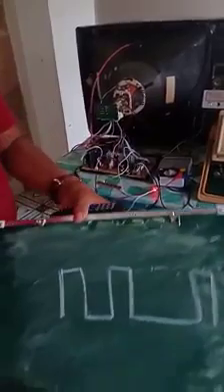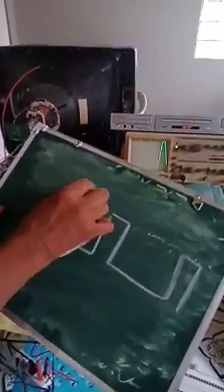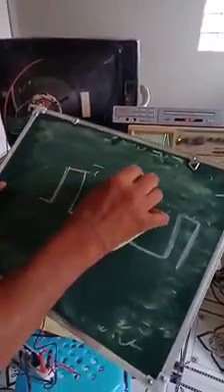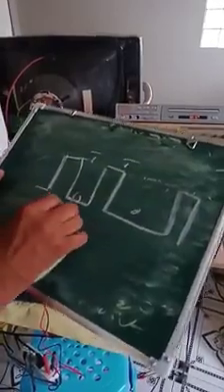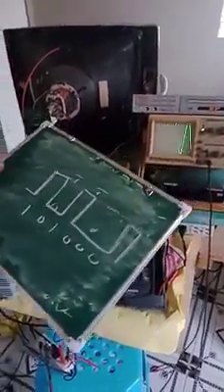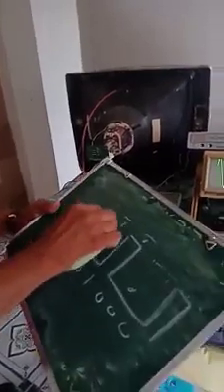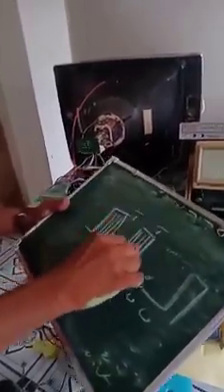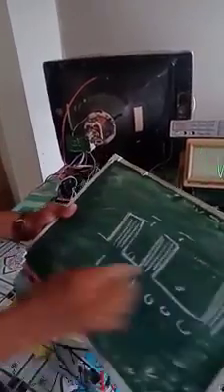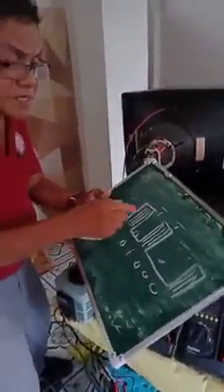But when you press this, the infrared LED emits light and sends pulses. We have here the pulses: 1, 0, 1, 0, 0, 0. These are the binary information being transmitted by the remote control, carried by a higher radio frequency, which is 38 kHz. So the pulses, the binary information, are being carried by the 38 kHz.